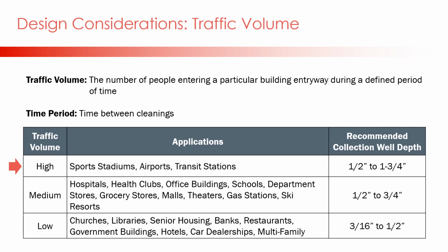Areas with high traffic in a short period require a deeper well. The deeper well will ensure the debris is trapped and not carried into the facility. At the other extreme is, say, a library. Traffic enters the building over the course of a longer period of time and extends the time between cleanings. Regular vacuuming with weekly removal of the mat for maintenance may be adequate with a small well depth.